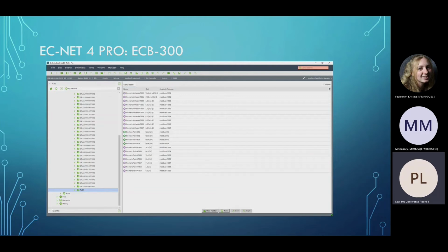What really does the conversion is the Fox that is associated with the station in the Jace. So Fox is Niagara's server, and it can do some magic and just say, oh, this point right here, that is modbus register 47,900, whatever it is. That's the power of Fox. I didn't configure Fox, Fritz didn't configure Fox. When you open a station, Fox is automatically enabled. It's the first thing that they set up on a station, the Fox server. So these aren't really modbus registers, but you can think of them like that. Fox does the magic behind the scenes.